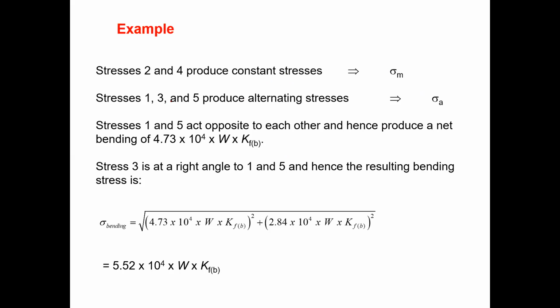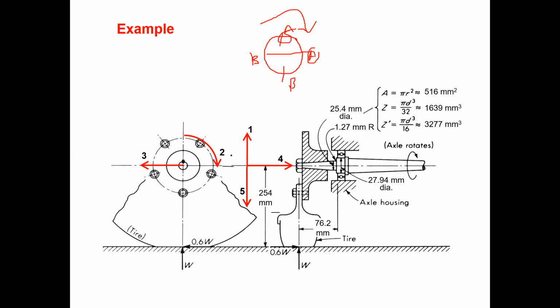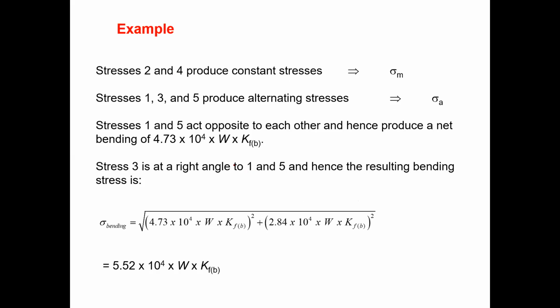So then what we need to do is get one equivalent stress for those stresses. So 2 and 4 in here, this is axial load, this is like a sigma x, this is like a tau xy. In here, sigma y equals 0. Then you can use the Mohr circle theory or that equation to find out the equivalent stress, one single stress. It will be the principal stress.